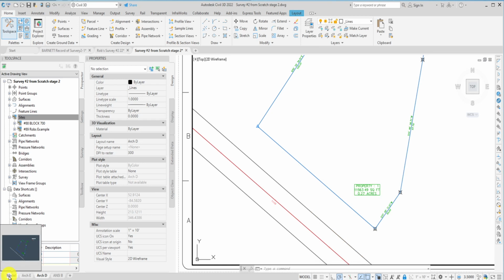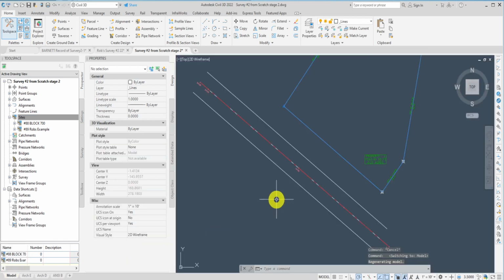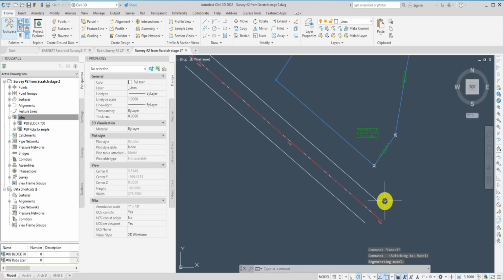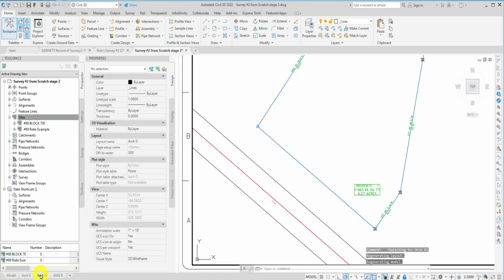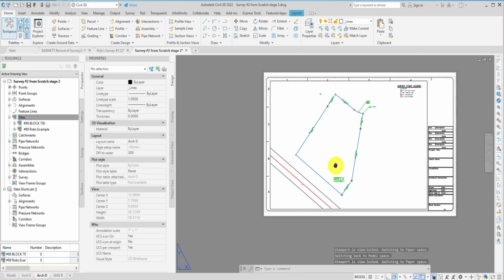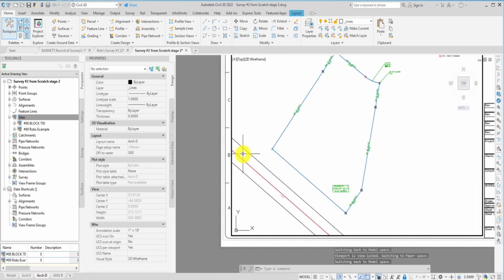I'm going to navigate to model space, and we can see that those offset alignments don't start down here. They start in from the endpoint, and they go all the way to the end. Just demonstrating what that choice was that we made back in our dialog box. But I'm still showing the whole road extending out on past the edges of the viewport, which is what I'm looking for. Okay, we've now created our second Civil 3D element.